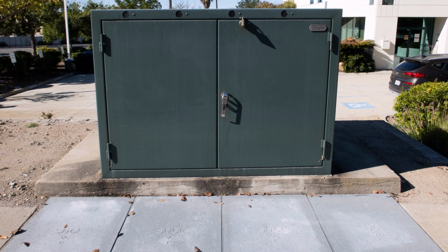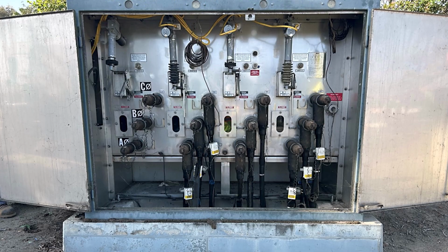Before we go, let's take a look inside of one of these real quick. This is a 4-way vacuum switch. You can see here, starting from the left, we have way 1, 2, 3, and way 4. Each set of 3-phase distribution feeder cables are connected to the switch bushings labeled A phase, B phase, and C phase. Way 1 in this switch appears to be empty since no cables are actually attached to these bushings.